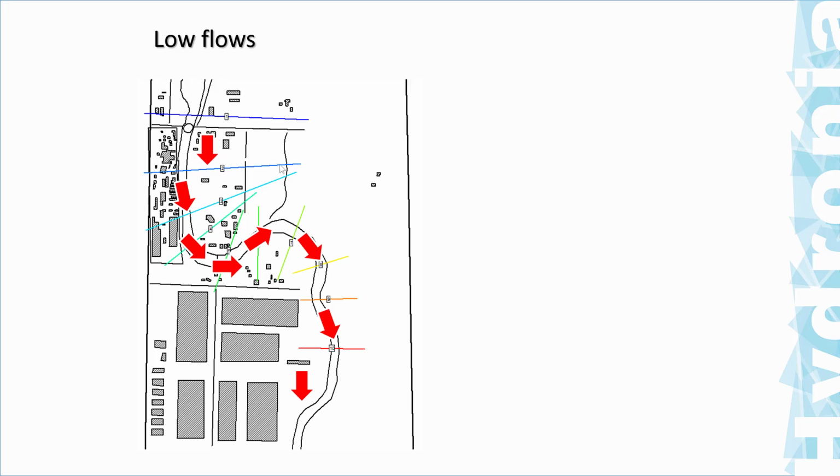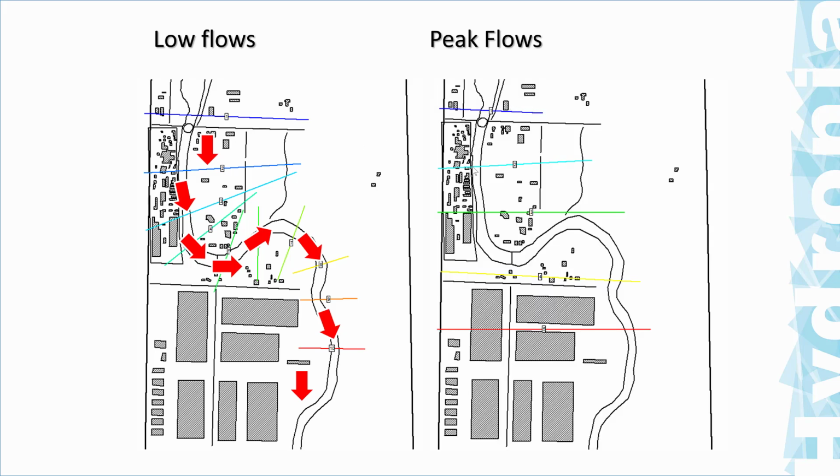orientation of the cross sections through the hydrograph, when you compute the full hydrograph, it may happen that for the peak flows, the flow may actually overtop everything, and then it goes through directly to the floodplain, and it flows in one direction, essentially going downstream. That would require having cross sections that are in different orientation to avoid the violation of the assumption of perpendicular flow to the cross section. But that is obviously not possible, because you cannot change the direction of the cross sections dynamically in a 1D model.